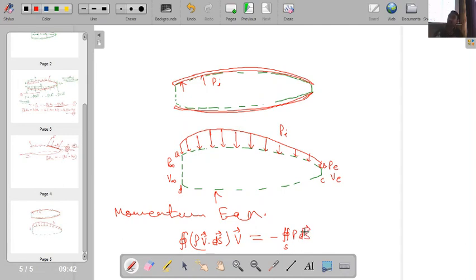Then, because we are referring over here to the situation where thrust force will be mainly because of the pressure distribution, that's why we will not consider the body force over here. Is this point clear? So body force also I will not consider. Now if I extend this equation for x direction, because we are trying to find out the force only in the x direction.